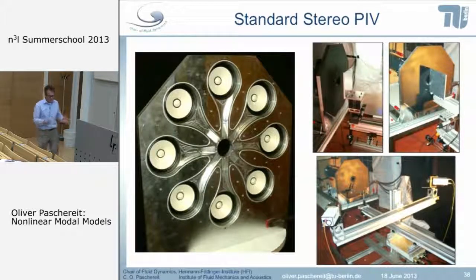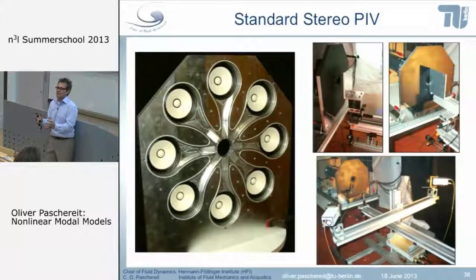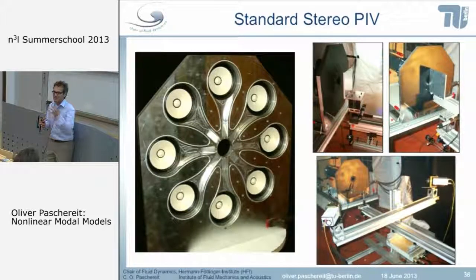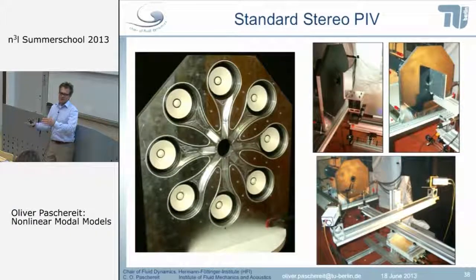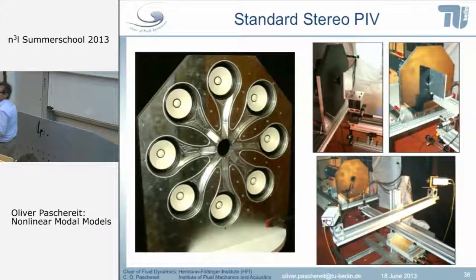And the basic idea is also an old one, because you can do beautiful things by this excitation of jets. For example, if you excite an axisymmetric jet, not a swirling one, unfortunately it does not work there. I can also explain why, because we did the analysis on this. But let's assume an axisymmetric jet, and you apply different mode forcing. So for example, a helical mode -1 and a double helix +2. So spinning modes in different directions. Then your circular axisymmetric jet becomes a triangle. So you get a different shape of your jet. Or combining a -2 with a +2 gives you a rectangular jet. So you can modify your flow features by this kind of excitation.